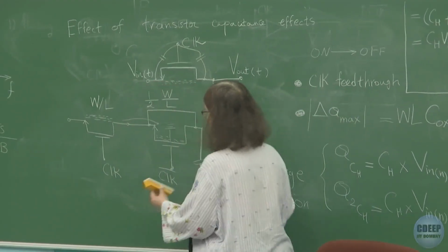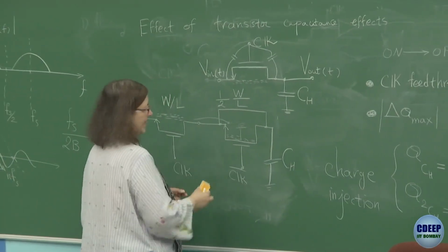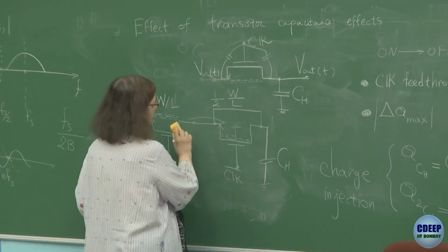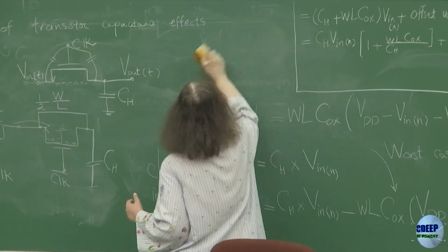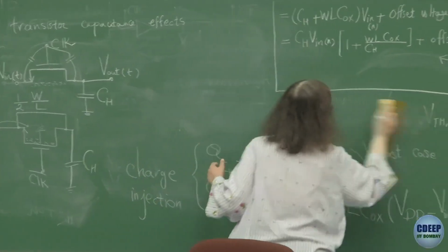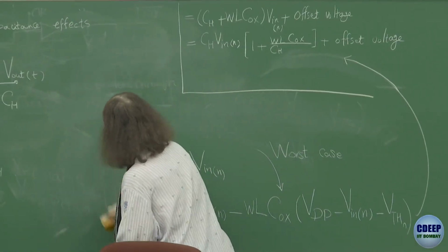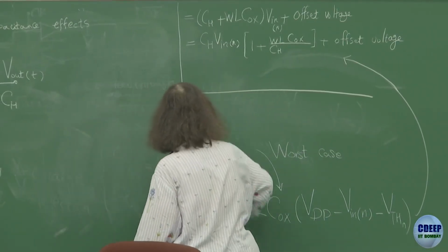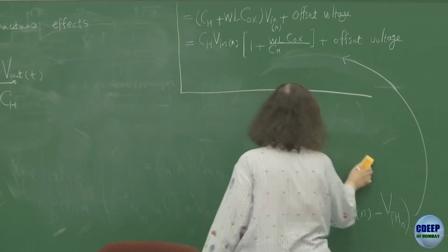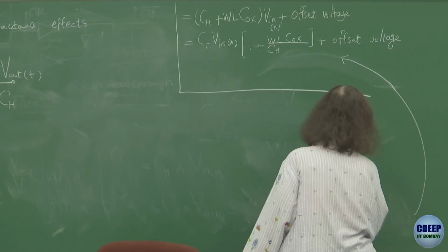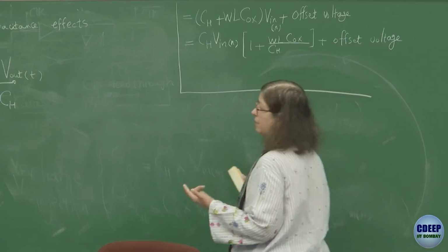In fact, if you want to show this circuit properly, it's better to show this dummy transistor vertical rather than horizontal. It will give you a better perspective. I draw it here. You see how it changes the perception of the circuit. See, if suppose entire charge comes, actually you may need to make larger W by L for the dummy transistor. We don't know how much, that's why they get it half.